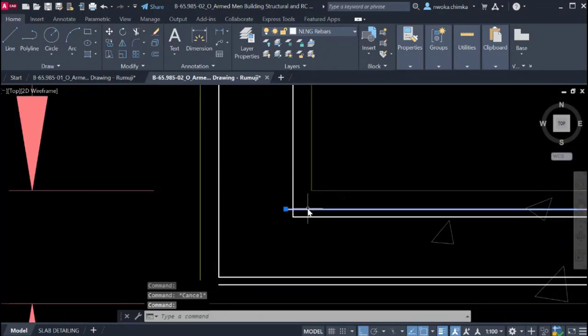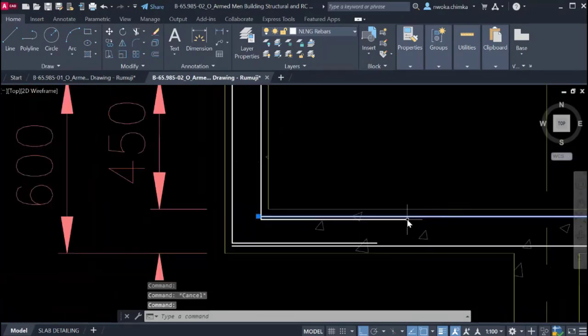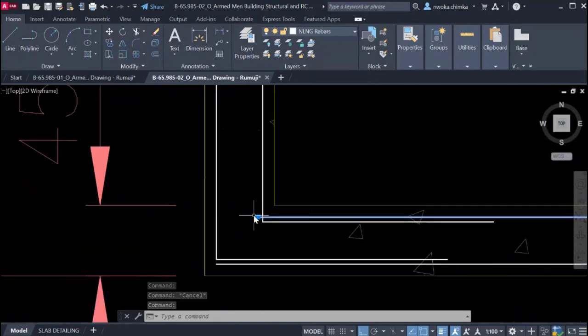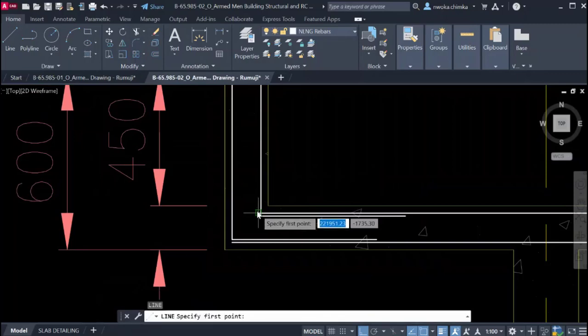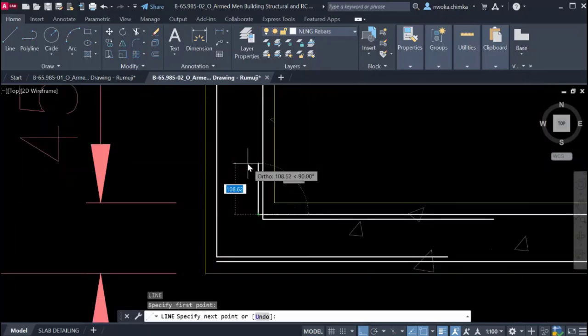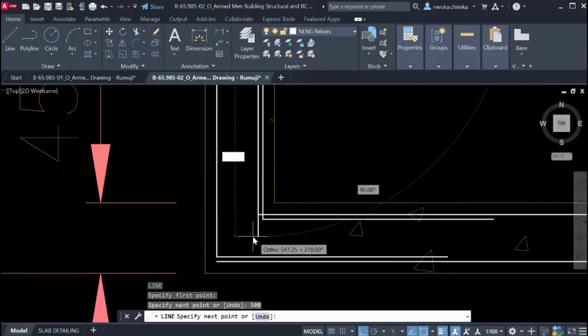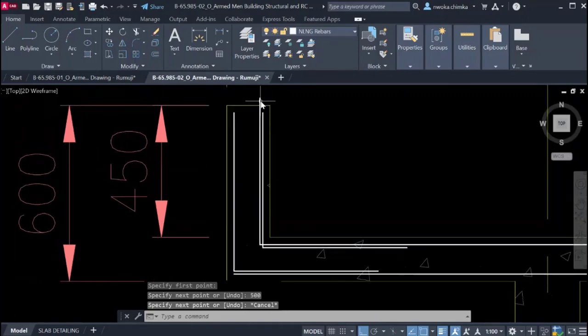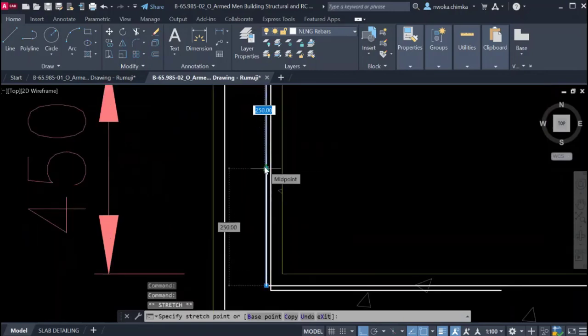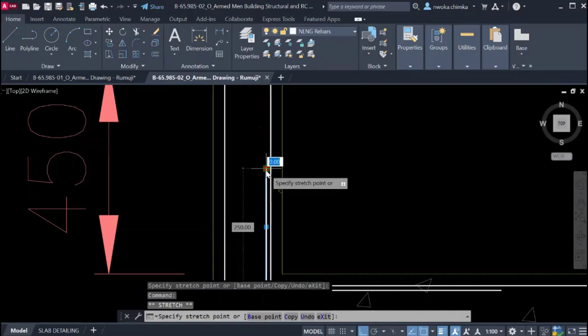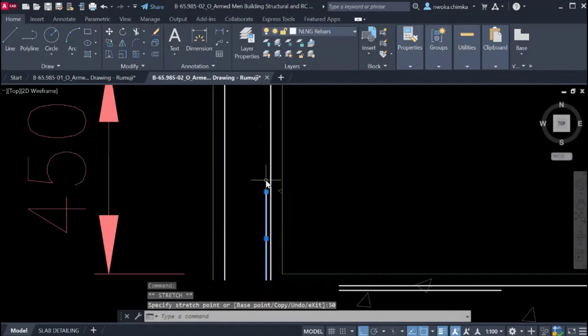Then this top reinforcement for this slab, we also go in and anchor inside this parapet to bring firmness. So we also lap this by 500, and then you can see what is happening here is already more than that. So we have to take half of it. So just go half, or we say 200. We go first for 250, then now reduce by 50.